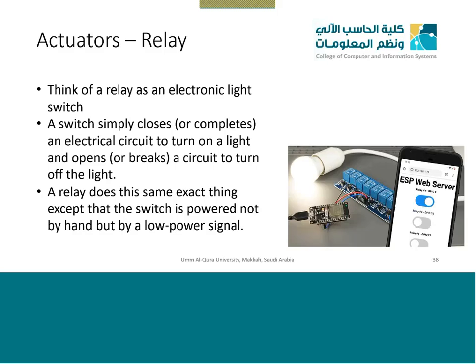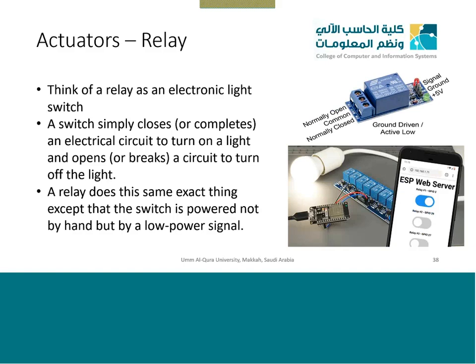So what is a relay? A relay looks something like this in the blue color. On one side you have the inputs from the device, the 220 volt device or the 110 volt device, which can be your microwave oven, it can be your light, it can be your fan, anything. On the other side is a ground and 5 volt, which is a fixed supply. You connect it to a battery, and then there is a signal pin.